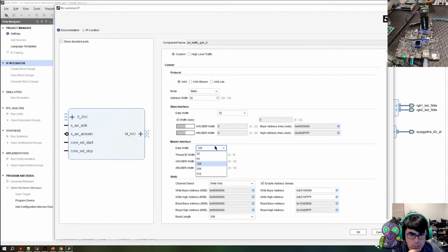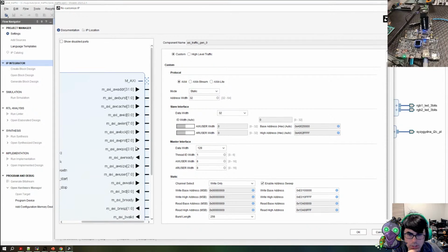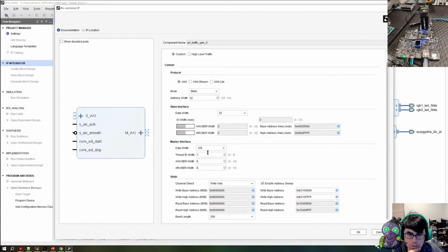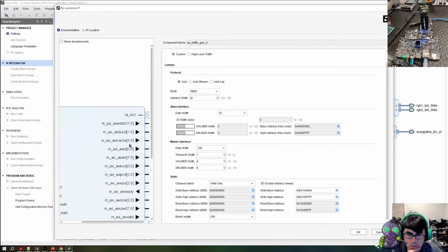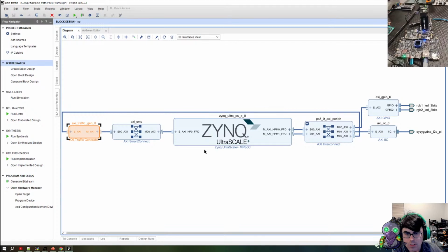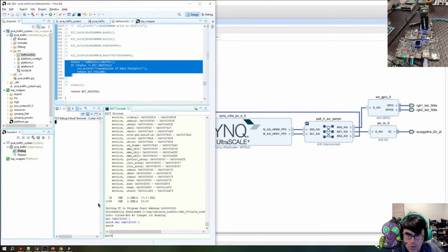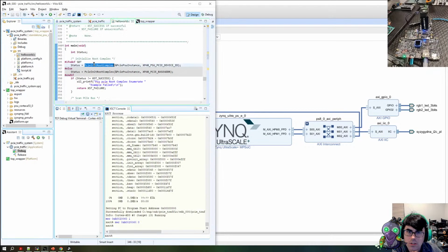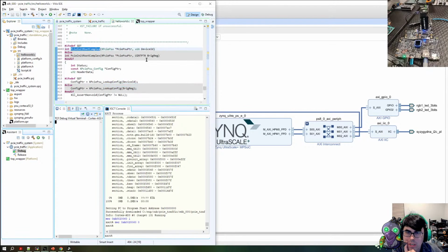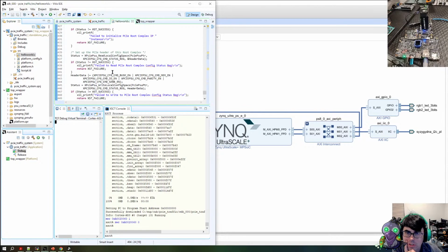Data width is 128. That's the bit width though, right? Yeah, so that's bit width. That's not it. For the first length I did 256, so that should be doing 256. So somewhere it's being scaled down. Maybe I'm not configuring it correctly for 128. Maybe somewhere in the root complex we can make sure.